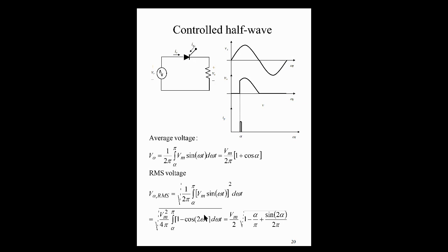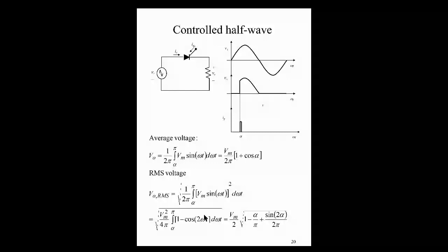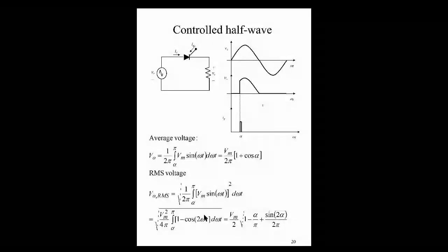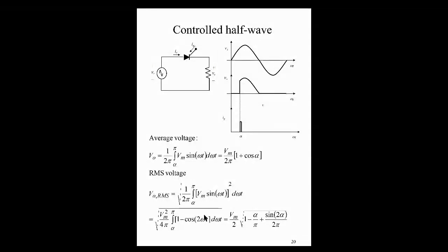We then look at the resistive, capacitive type rectification circuits, that is uncontrolled. We look at the different waveforms, the voltage and the current, and the calculations associated with them. How do we find the peak current through the diode, the capacitor, and so on. All right, so we will stop here.